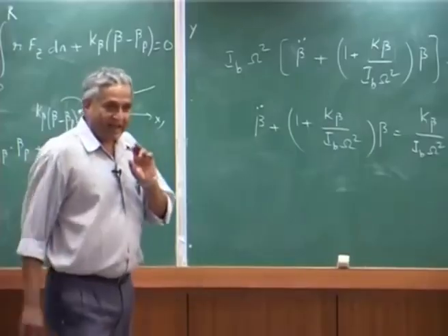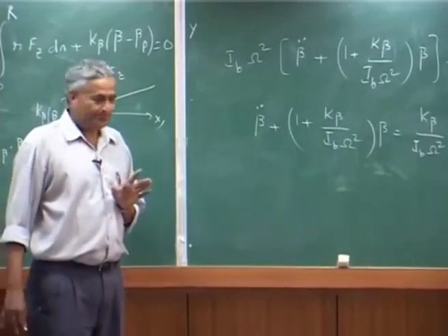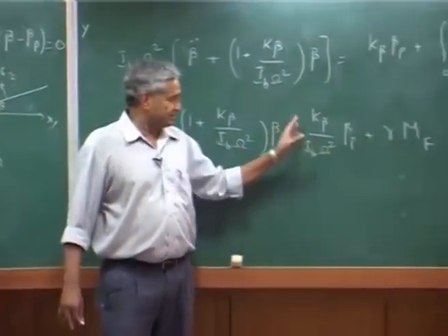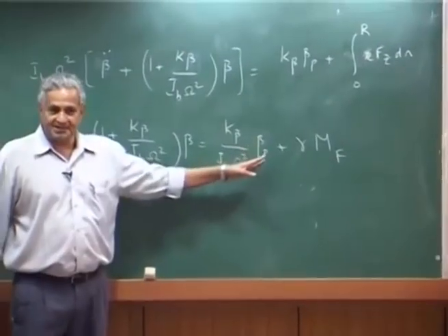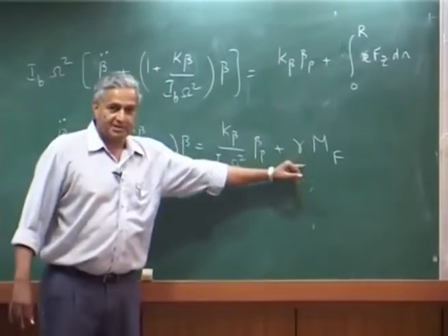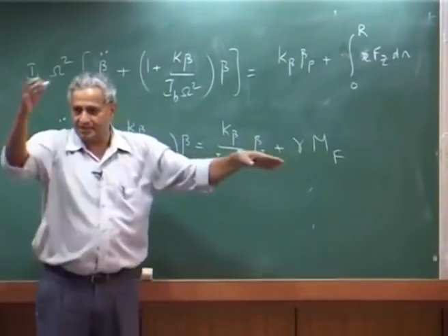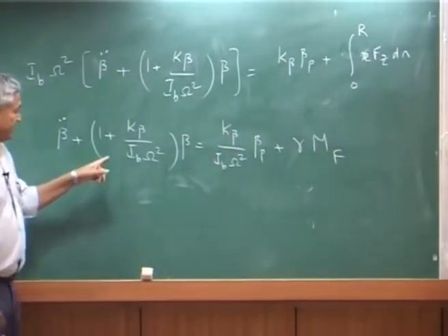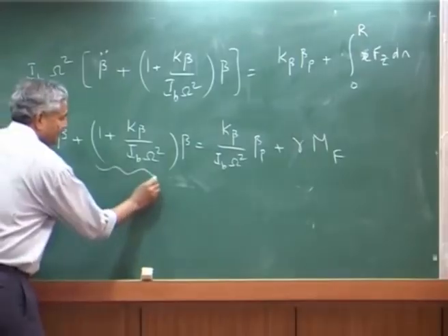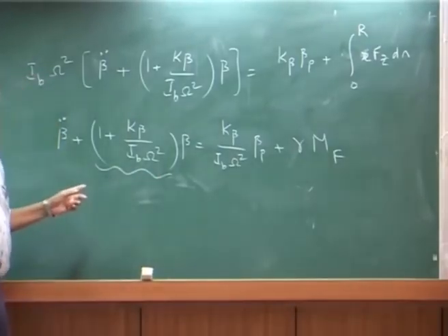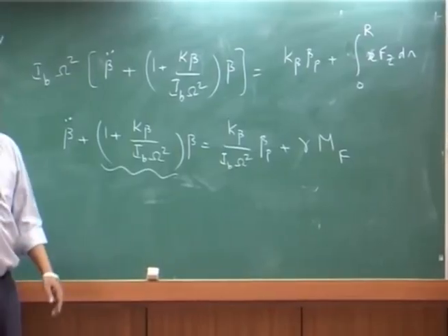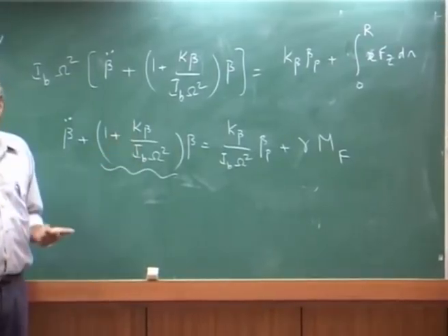Okay. By adding a spring and a precone, I am getting a constant moment on the right side. This is the aerodynamic, because gamma is the Lock number, M_f is all those theta_I etc. This is my now new natural frequency in flap, which is actually more than 1.